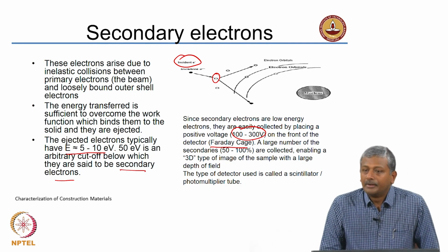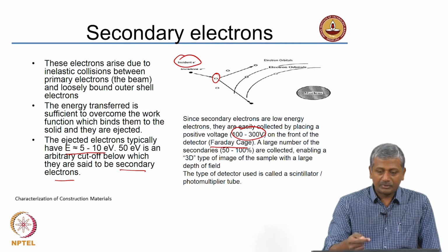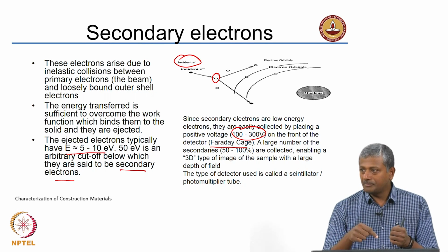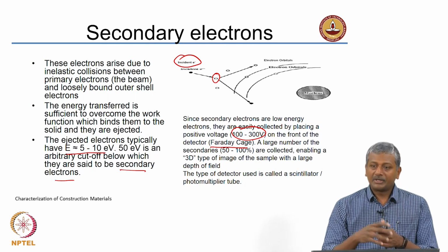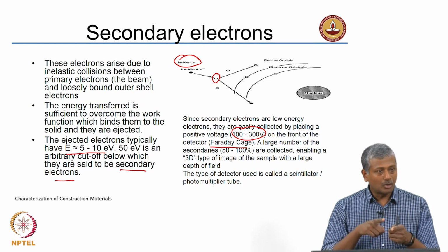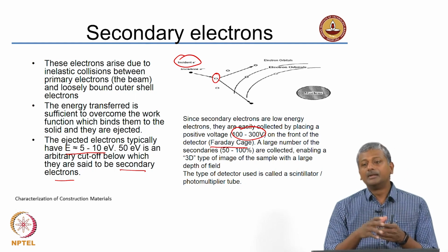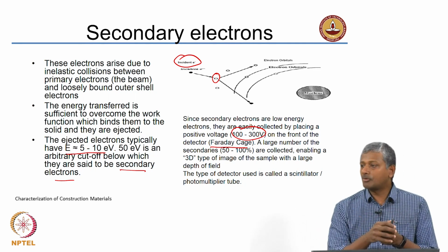So, exactly try to displace the atom from inner shell. Yes, yes. So, I will come back to that. So, the question is, in X-ray diffraction, the incident electrons which are generated in the X-ray tube knock off the inner shell electrons of the target metal, because of which you generate characteristic X-rays. But here this beam is only knocking off the external electrons. There will be internal electrons also, we will come to that in just a minute, but external electrons getting ejected are loosely defining the morphology of the object.